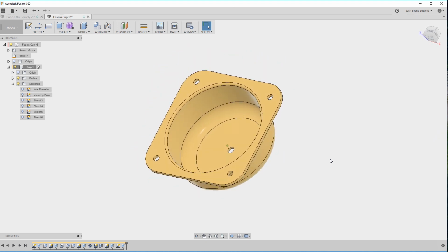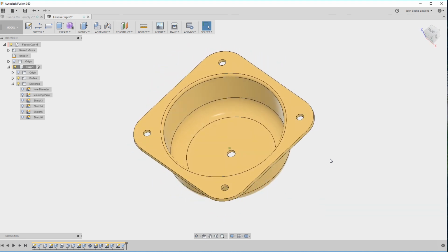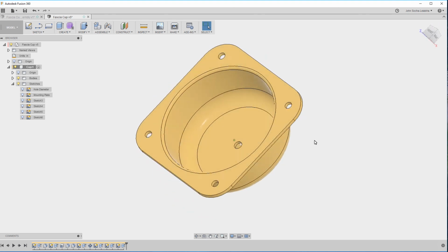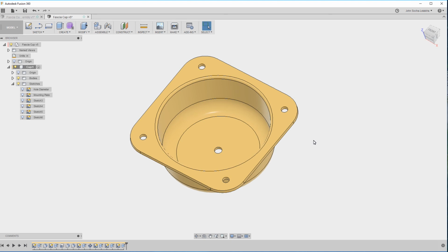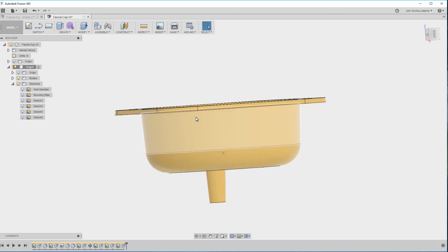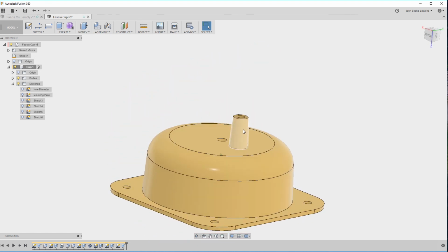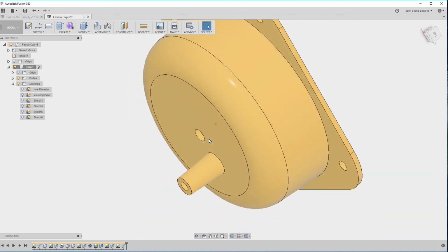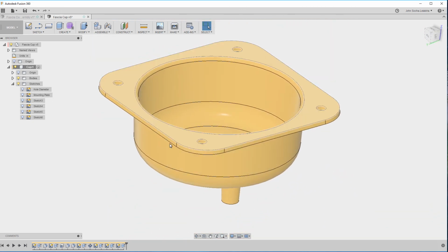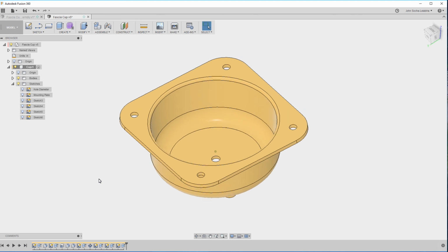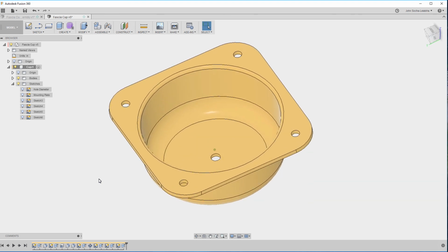Now the next step after this will be for me to start designing the mold. I'm also going to make a few other changes probably, but the important thing about this is to think about, if you're going to make a mold, to try to put the draft angle into the different areas as you design it rather than after the fact. I find that it takes a little bit more time to do that up front, but it certainly saves a whole lot of time later if you want to start making revisions.